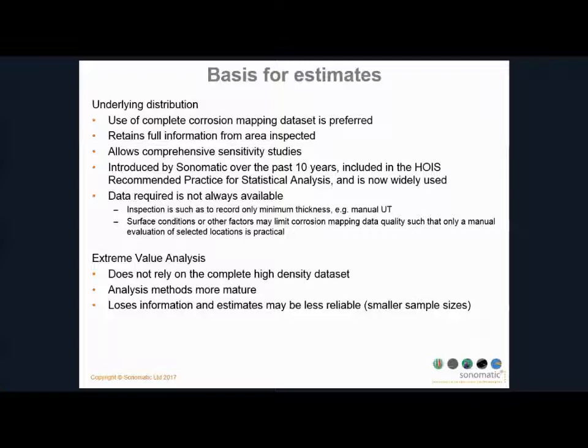The analysis methods behind extreme value analysis are more mature, and it's used across a wide variety of different fields, not just for inspection. And the analysis approaches developed in other areas are relevant to inspection. One of the issues with it is that it does lose information compared to using the underlying distribution, and your estimates may also be less reliable because you end up with smaller sample sizes in many cases.